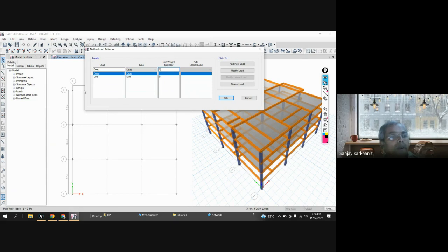Now, if I go to live load, you cannot give multiple instructions to the software which are contradictory to each other. So that's why here what we are following, see every time, whenever you are applying any primary load case, software will apply self weight into it.